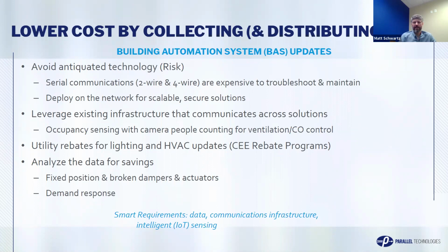The equipment on site is a couple decades old at this point, and what we've found is that there are really inefficient operations in the building that have really inched up over time. So dampers on these VAV boxes have sometimes been fixed in their position. People will put a screw in them. They might remove a linkage on the damper. They might break the actuator so that it doesn't work. We've seen all of these things in this building.